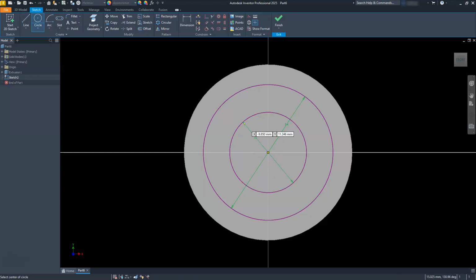All right, so from here, all I need to do is place 2 points located, one on this circle and one on this circle, right? We want to make sure that they are vertical, so I'll select the vertical. I'll also confirm that I'm getting these dotted vertical lines here. So I'll select this point to that point, and then I'll select this point to that point, right? So you can see that all of them are vertically in line with here.